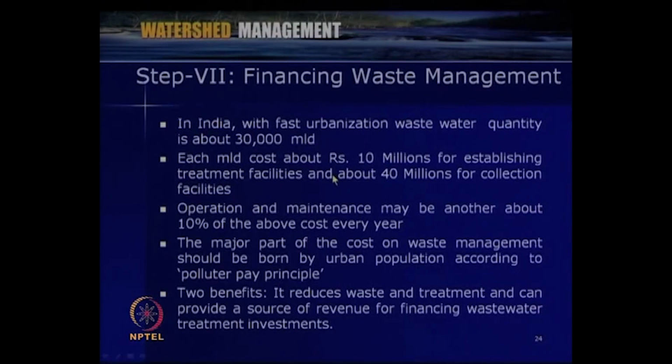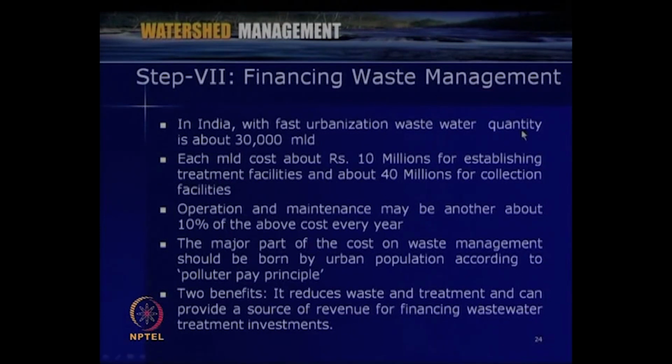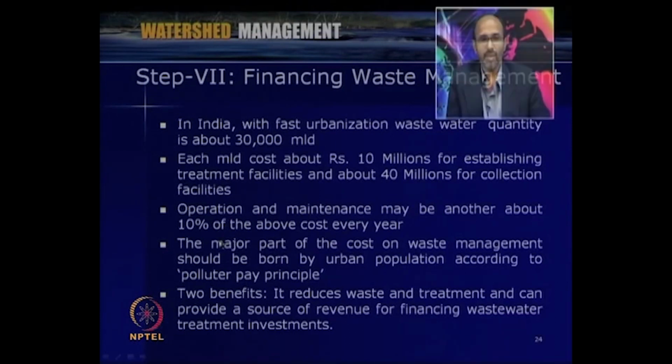So, we have to see how much money is available, how we can economically do things. In India, with fast urbanization, wastewater quantity is approximately 13,000 million liters per day. Each million liters per day costs about 10 million rupees for establishing the treatment facilities and about 40 million for collection facilities. Then operational maintenance may vary about 10% of the above cost.